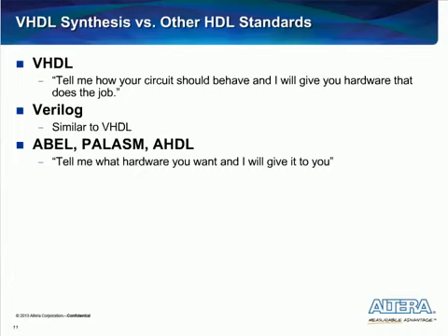VHDL supports both methods of designing, both by inference and by instantiation, which is what makes it so powerful. By simply describing the functionality of a circuit and letting the synthesis tool build it for you, you can produce very powerful functions in just a few lines of code. Doing this using a structural language is much more like programming in low-level assembly, with the circuit having a very specific implementation, so changes to that implementation do not scale easily and require much more effort.